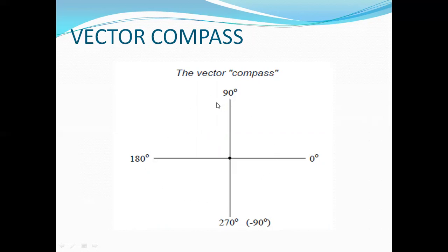If we rotate the vector in the anti-clockwise direction, from 0 to 90 degree, 180 degree, and again to 360 degree, the alternating quantity from 0 to pi, that is 180 degree, constitutes the positive half cycle. For the negative half cycle, from 180 degree to 360 degree constitutes the negative half cycle. And one complete rotation of this vector constitutes one complete cycle of an alternating quantity.